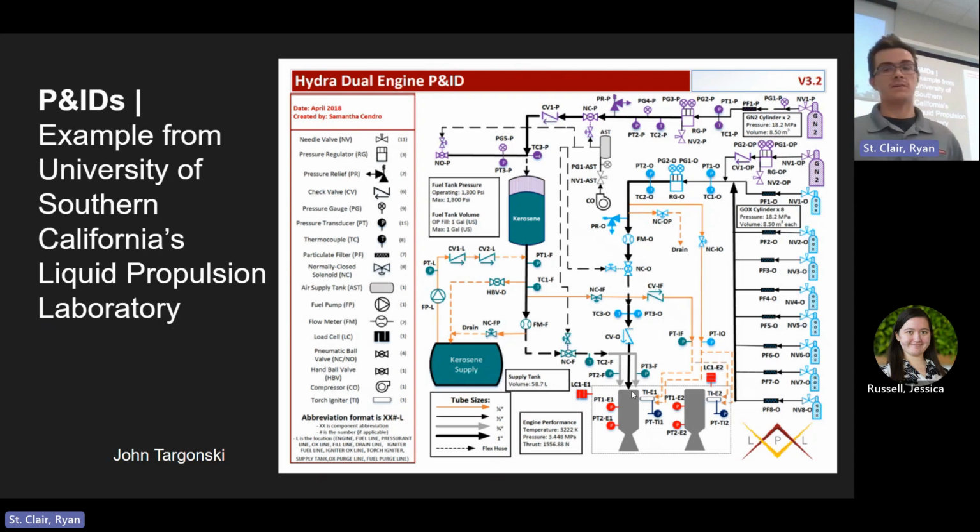And where's the oxidizer? Because you need fuel and oxidizer. It looks like you follow this line up here. It looks like there are gaseous oxygen tanks here. You've got particulate filters across each of them because, again, they're concerned about introducing particulates into this high pressure oxidizer system. So they include these filters right here, and they go across here through this regulator. It looks like through a flow meter, again, a check valve.